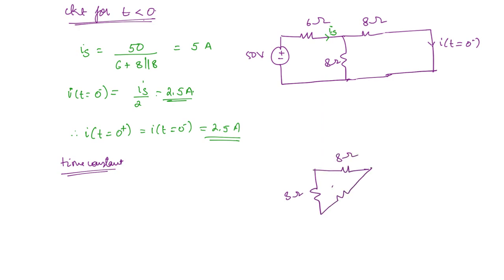Now here we had 32 ohms and here there was 32 ohms, and we have to look through the open circuited terminals of the inductor. This is RTH. Here you can see that there are 3 resistor combinations in parallel. This is one resistor in parallel, this is one resistor in parallel, and both of these resistors which are in series are parallel to these both.